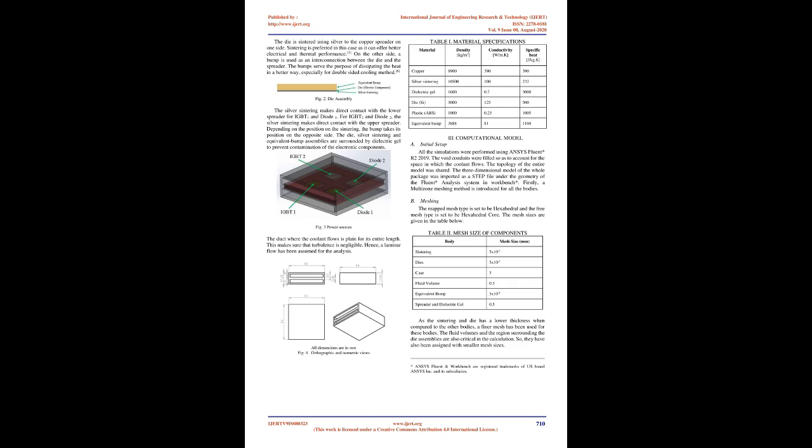This arrangement consists of a case made of plastic which serves as a passage for coolant flow above and/or below the module. The entire packaging is contained within the case. The package consists of copper spreaders, dielectric gel, silver sintering, dies and bumps. The coolant flows through the passage in this arrangement such that the coolant has direct contact with the spreaders on both the sides. Fig.